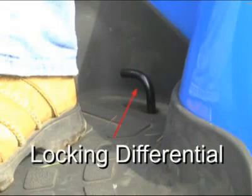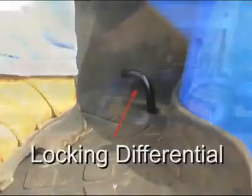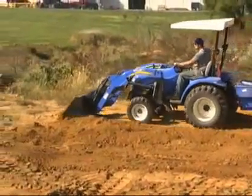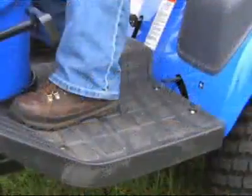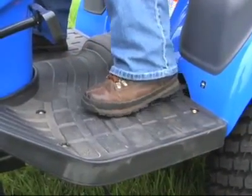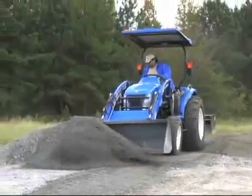Another axle feature is a locking differential, or diff lock. This simple system increases traction by forcing both wheels on the axle to rotate in unison, regardless of traction or terrain. On New Holland compacts, the diff lock lever is positioned for quick and easy activation anytime you need extra traction.